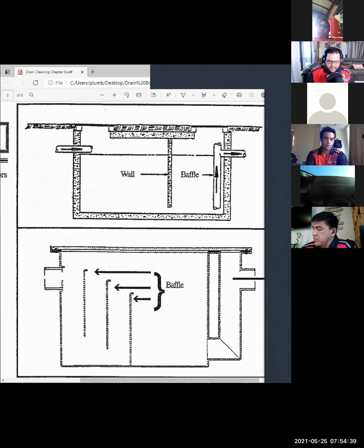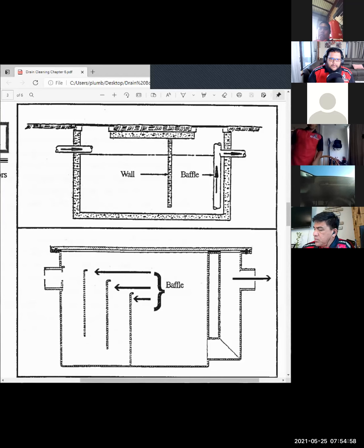Hey, Josh, let's point out one more thing here. And you guys in the field, Bennett, you've been around a long time. Let's just use the inlet of this interceptor where it says baffle, and you've got your vertical pipe and your horizontal, and what you can see is like a T. If you don't see that in there, that grease trap's not working properly. It's not designed properly. It wasn't installed properly. So guess what you need to do? You need to sell the guy a correction.